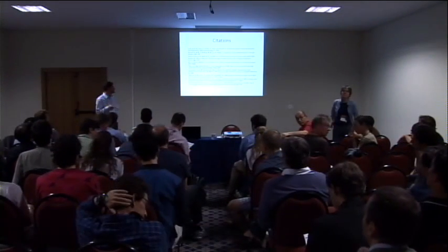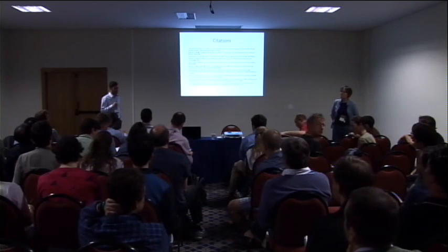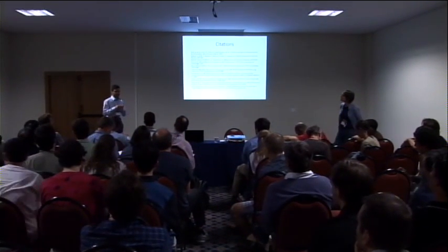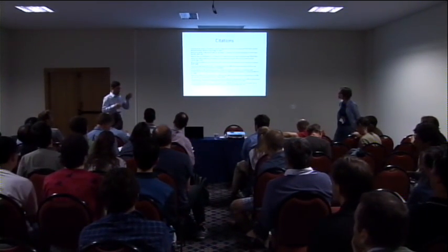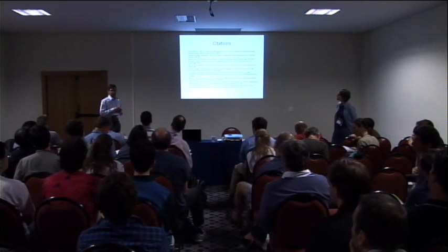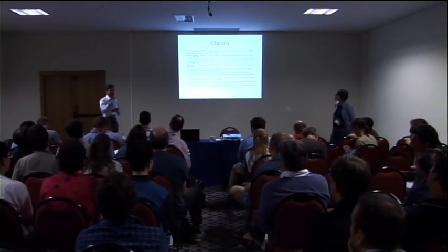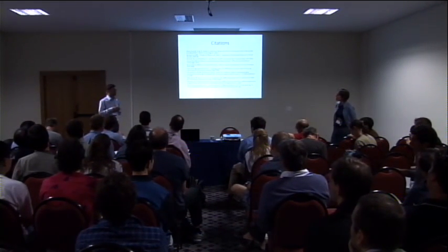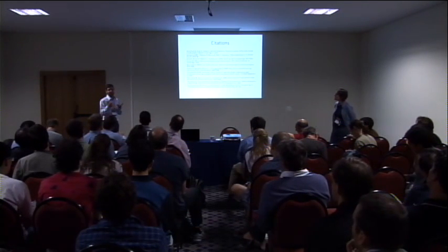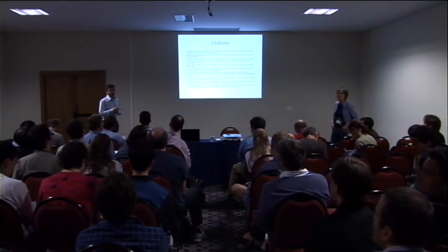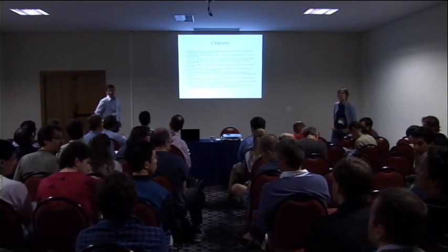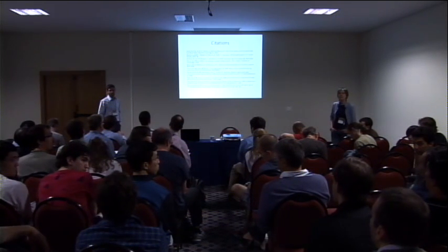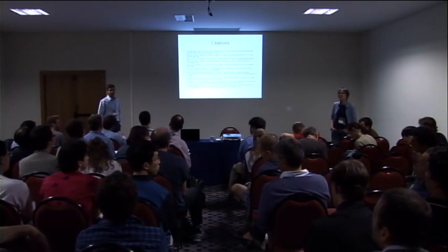Right, so that's a very good question. They're definitely coming close to each other, but I think one of the issues with a lot of motion planners is that they're just concerned with achieving some goal state. But they don't do so by minimizing some criteria in many cases. In fact, there are some recent developments showing that they actually compute optimal paths. So, for example, RRT star.